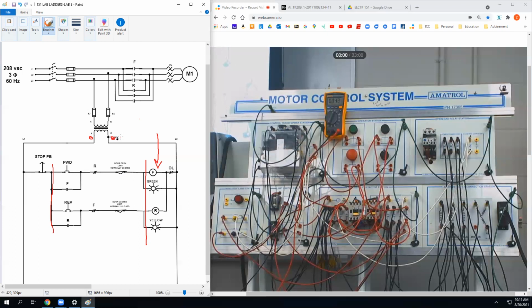Well, look at it the other way. Is any of this open, through that coil, through that, through that, through that? Right now, with that de-energized, I would read continuity across that, backfed through the entire thing. All of this stuff is closed. A transformer secondary winding is just a winding of wire, right? So I would read continuity across that going that way. Which is why you always isolate it. Take the wires off and check it.